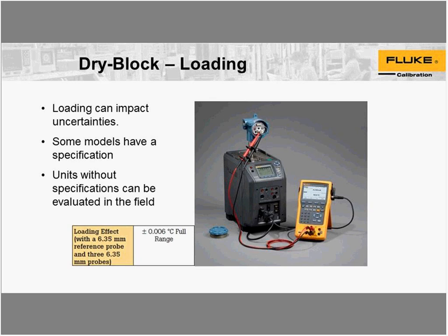An example would be one of our handheld dry wells. We do have a model with a half-inch hole design, but I would not recommend a high temp half-inch by 12-inch unit and mating that with it as a good solution. The mass of the probe or unit under test is going to basically outdo the design of that well.